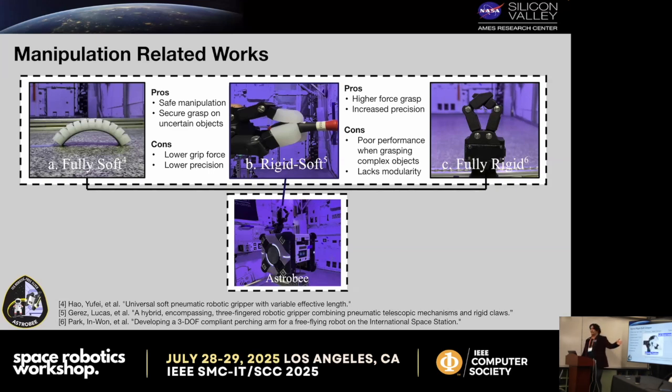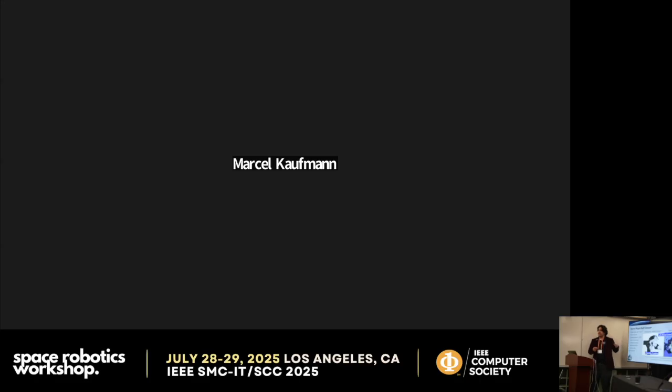For design, we actually got to fabricating this gripper. This gripper itself is a 3-finger gripper with rigid claws, and it is able to leverage some of the things in soft robotics, like pneumatic inflation and actuation, to conform around an object within the claws pneumatically. It's still tendon-driven, so it's a 3-finger tendon-driven, 1 degree of freedom gripper, and as I mentioned, it can pneumatically conform around the object in the grasp. But right now, it's an open loop system, so there's no feedback going to it.